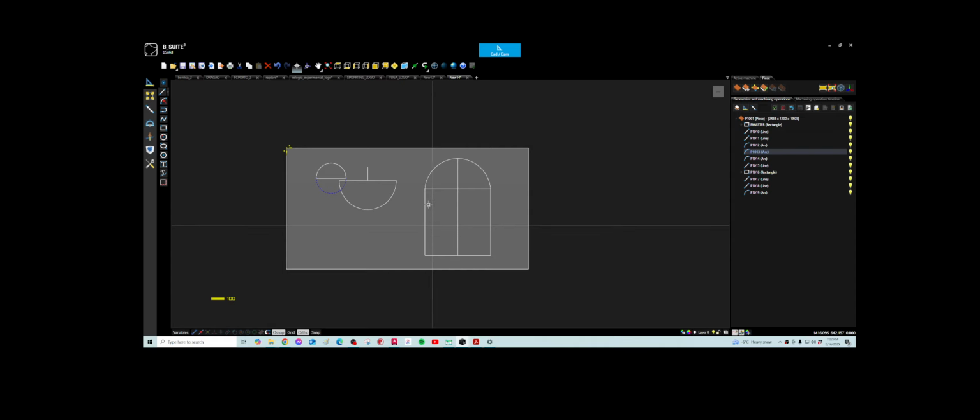So what you need to measure is the length from the beginning to the end of the window, and then you go to the center and measure how much you have from the center to the top, and then that's all you need, the length and then the center to the radius, right? And then when you use this tool here, this way, 3 points, this would work perfectly. I've done this many times. Sometimes I have templates, so I use the formula. I put the template on top of the machine. I measure the length. I measure the center, how much it has.